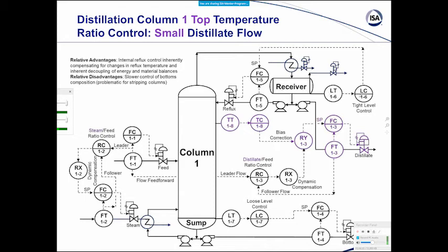So this level controller has to respond to very tiny changes in the level, and you need a very sensitive level measurement as well. And maybe this horizontal drum is not really the best situation, because you have a huge change in flow rate over a period of time before you see much of a change in level, because it's a horizontal drum. You need a very sensitive level measurement. I would say for tight level control, you probably want to go with